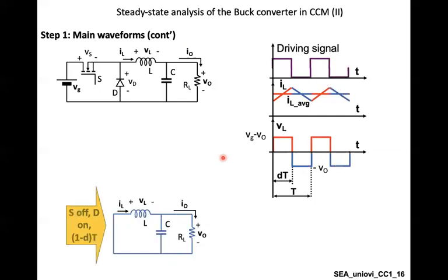So this is the current across the inductor, and this is the voltage across the inductor. Now, using Faraday's law, using the fact that v equals L di by dt, so di by dt is simple. This is di, the incremental change in the current, and dt is either this portion or this portion. For simplicity, let's consider the blue portion. So di over dt, what about this duration?